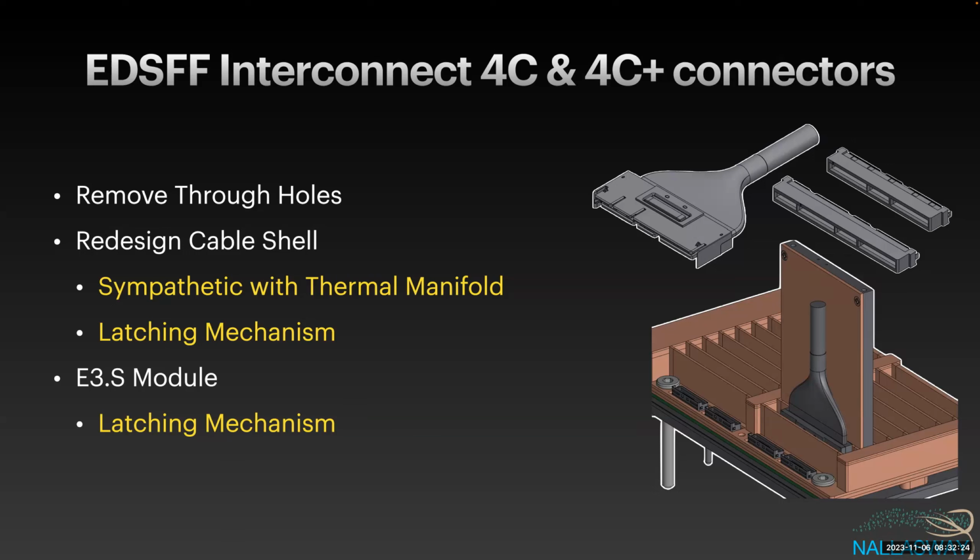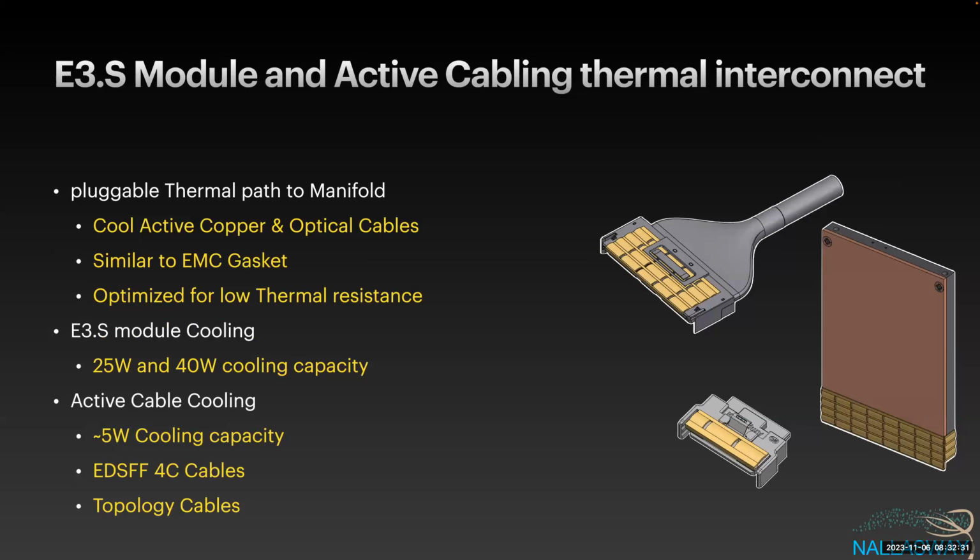From the thermal management side, this is going to be entirely direct water cooled, and the idea is that we recover all of the energy in the water, and we maintain an output temperature of 65 degrees C for thermal reuse purposes. And so on these lower power modules, we're looking at a conductively cooled path to a local water channel, which is a manifold which carries water nearby. So we want these to be a pluggable thermal path to the manifold.